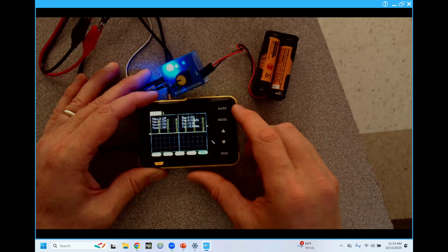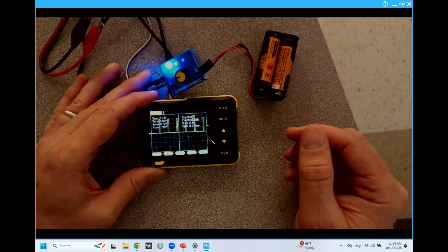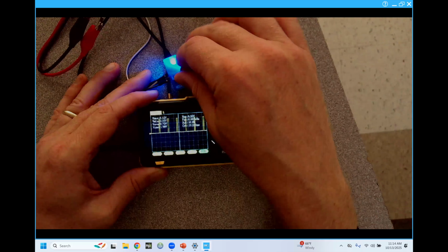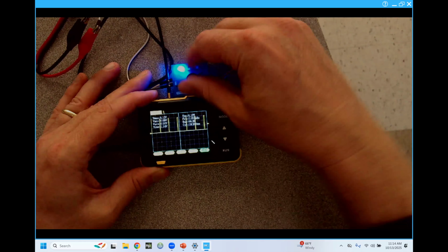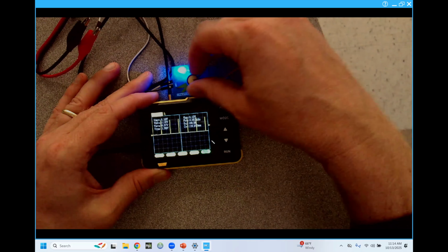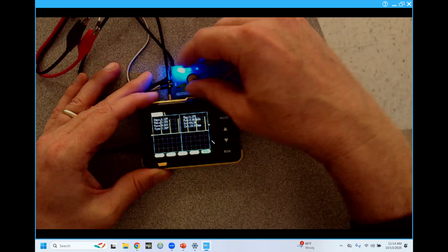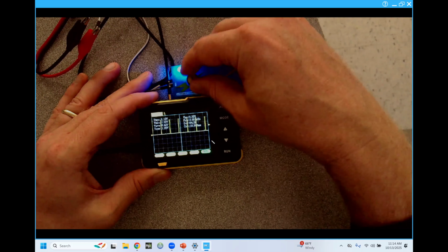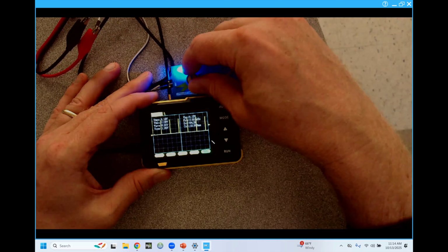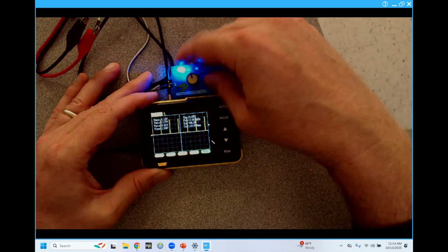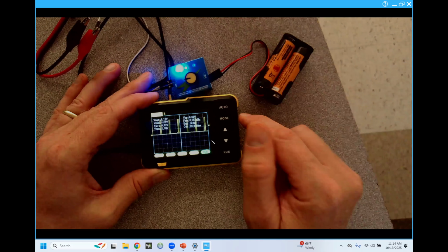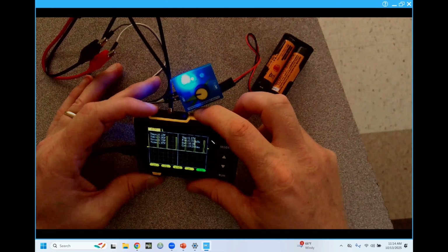Lots of pulses. And so as I turn the knob, those pulses get narrower and wider, but the spacing between the pulses is the same. So the pulses are coming in at 50 hertz, and the pulse width is either 1 or 2 milliseconds, depending on the knob. But let me see if I can do better. We have a little bit of time.